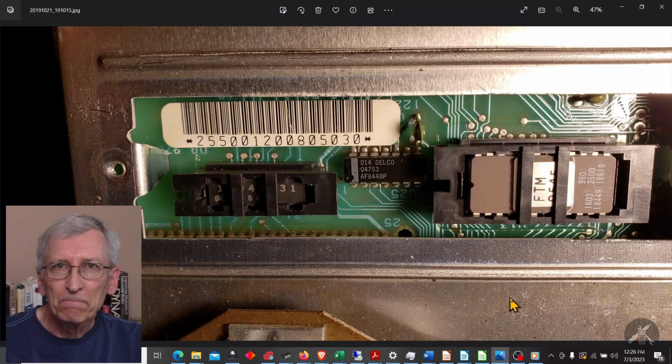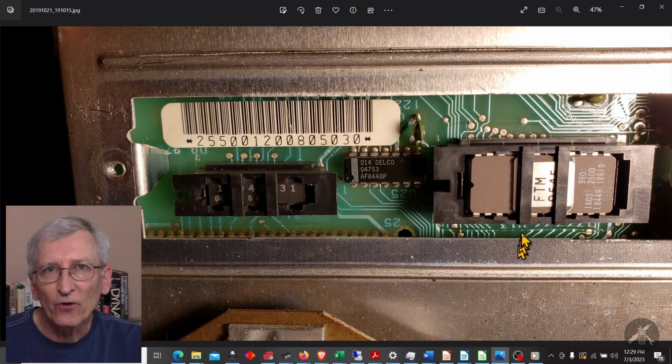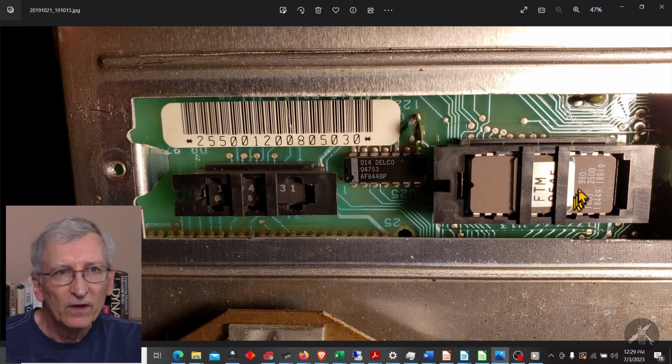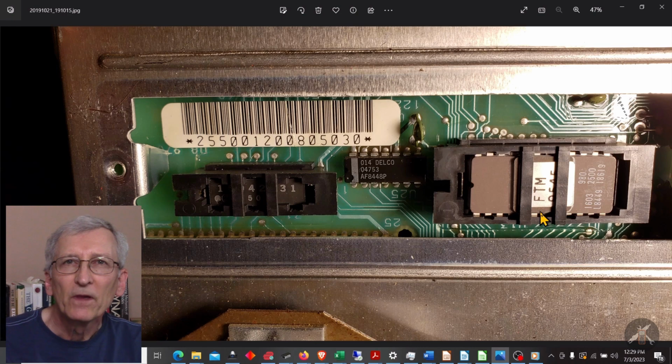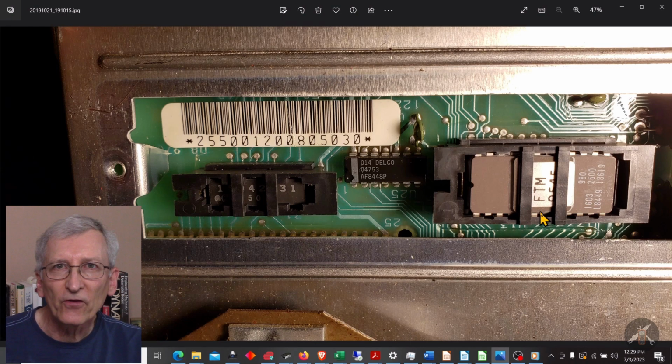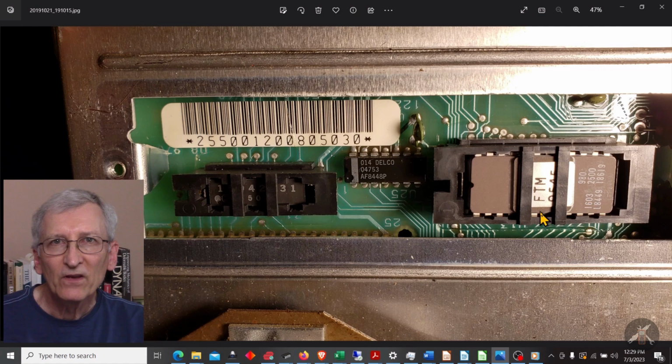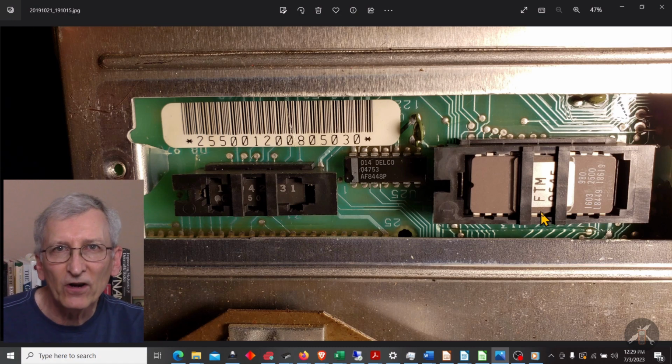If you go to your ECM and you remove it from the car, or pull it down out of its storage location and open up the little door on it, you can see over here this is the PROM, this is the calibration chip. And General Motors has a thing they call a broadcast code. A lot of times, got to be a little bit careful, oftentimes the broadcast code and an RPO will match. Sometimes they'll be different.